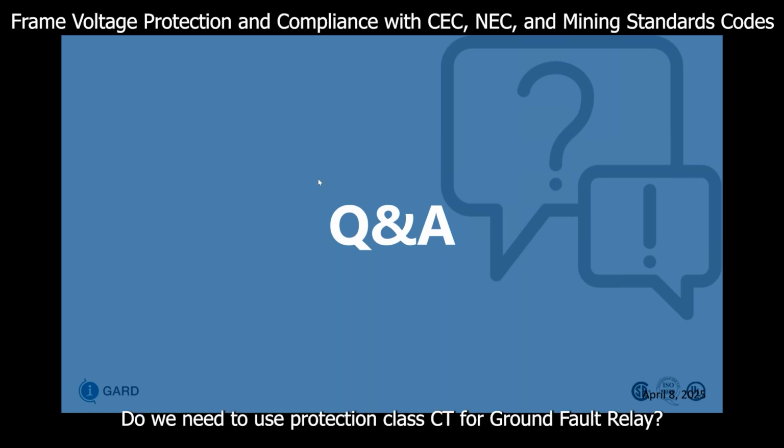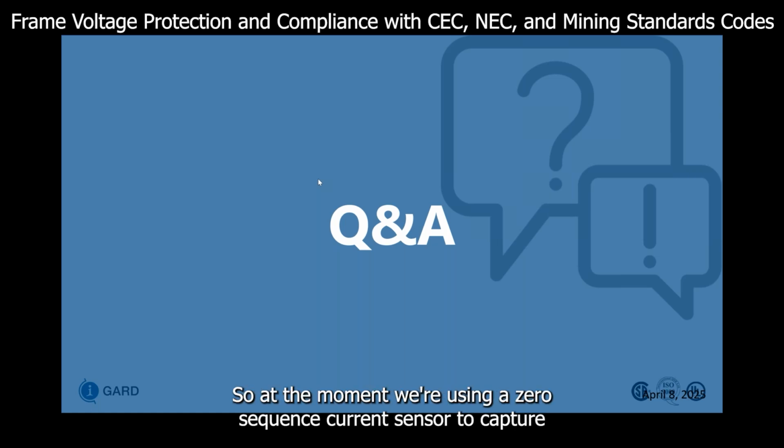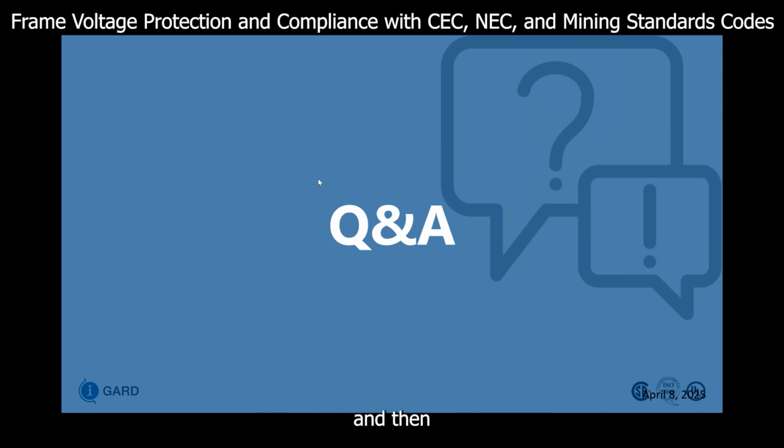Do we need to use a protection class CT for a ground fault relay? Not necessarily. You can use a zero sequence current sensor. At the moment we're using a zero sequence current sensor to capture the vectorial sum of the phase currents that are flowing through that CT window and then pick up the fault current discrepancy.